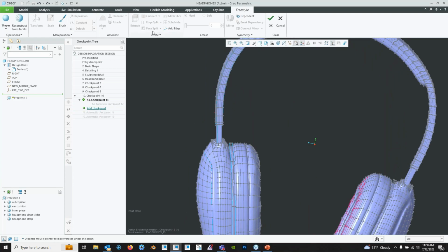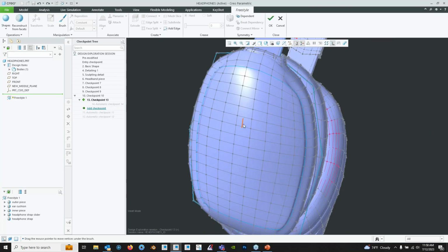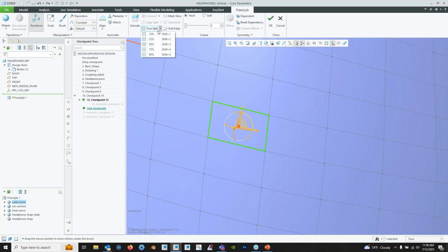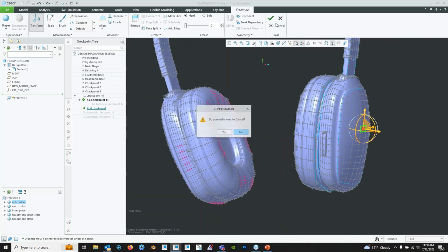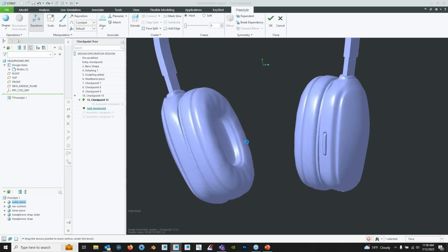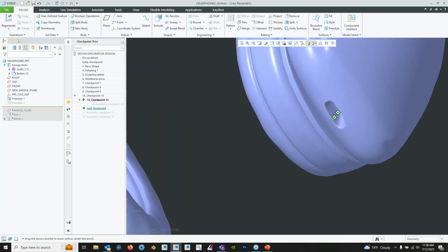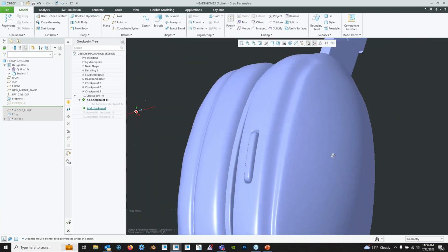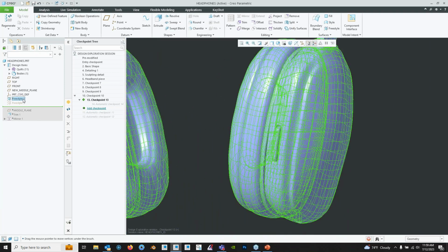There's this face split tool right here if you need an inset. So if I have one of these faces selected, I'll change my selection filter here. This face split can inset one of these squares, and then it'll allow me to get geometry like a hole or something that allows me to set it in, and then use the push tool to get something like this charging port right here, or I could continue to use it and get a button.